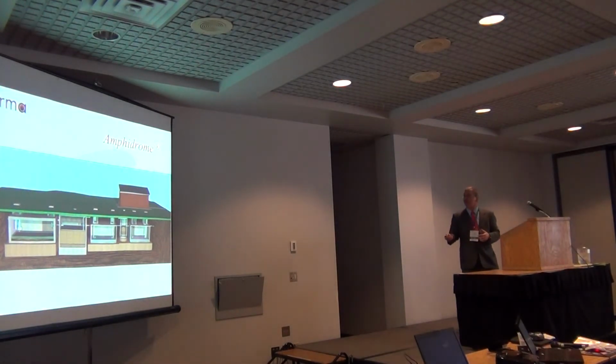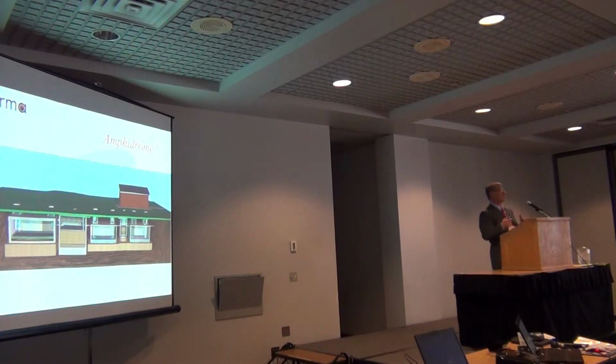The technology that we recently got approved in Minnesota is this amphidrome system, which is a deep bed sand filter. The sand is about 3 millimeters in diameter, and it has a very high specific surface area, so you end up with very high biomass concentration.